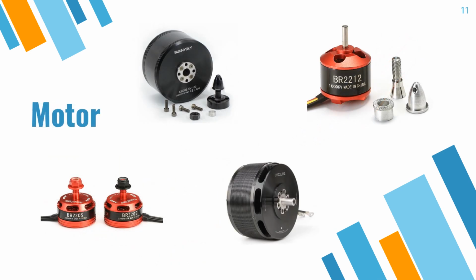Alright, let's talk about motors now. The most commonly used type of electromotors among drones is the so-called brushless motor. A brushless motor is basically an electromagnetic core with a permanent magnet around it. When electrical energy is applied to the different coils of the electromagnet, then through a magnetic field this is converted into kinetic energy of the permanent magnet around it. So it's basically a rotating magnetic field that causes the motors to spin.